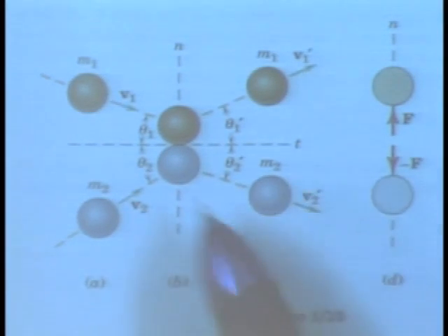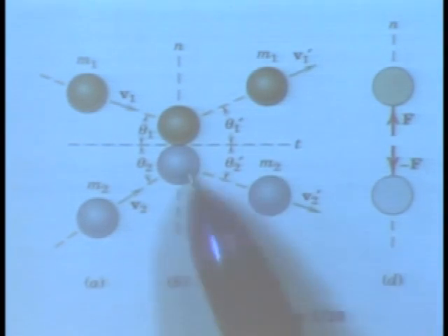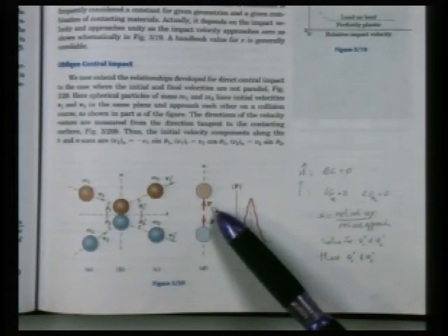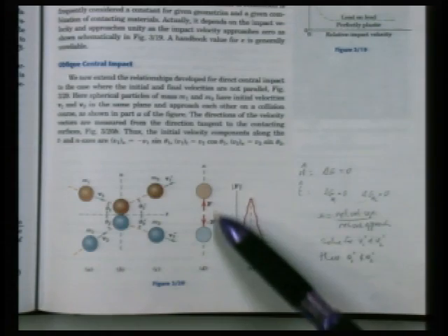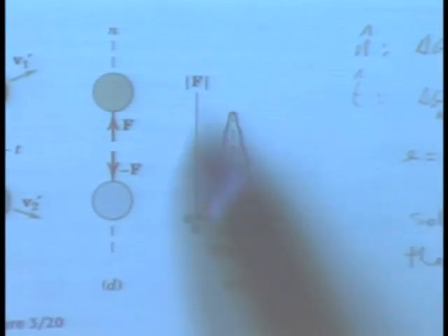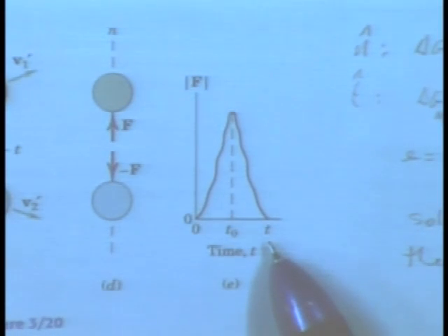So once we have that defined, that establishes a unit normal direction, and then the two masses will interact with one another as shown right here, where they have equal and opposing impulses in the normal direction. And here's what an impulse is: in an impact condition, it's typically over a very short duration of time, on the order of milliseconds, several milliseconds.